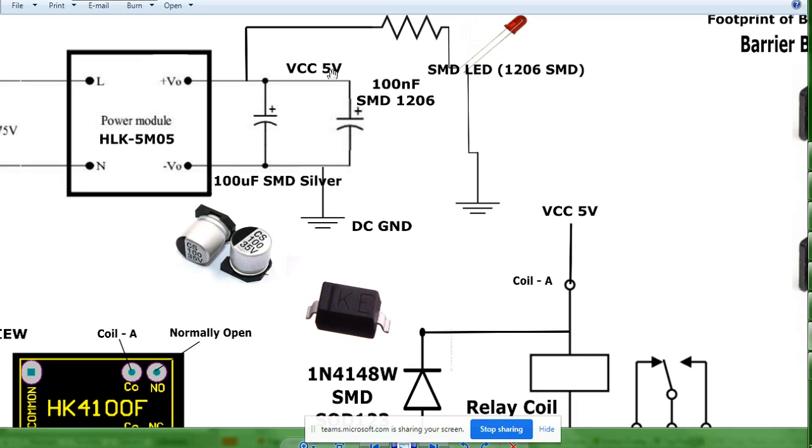But the small surges, such as a transistor turning on or something like that, or small noise, are going to be handled by this small capacitor, which is 100 nanofarad. You can call it 0.1 microfarad. So they have two different roles. I don't know how many of you have gone through the circuit analysis course and have an idea of what capacitive reactance is. Capacitive reactance XC is equal to 1 over 2 pi FC. Now the capacitive reactance of a larger value capacitor is going to be different than that of a smaller value.